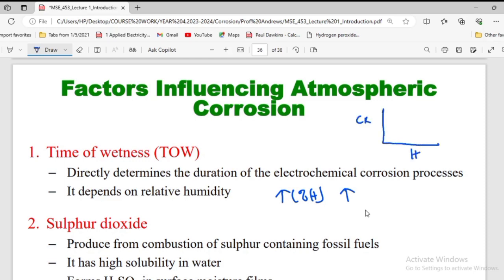So we have the humidity, in percentage, and as the humidity increases, the corrosion rate also increases. But at 70%, pollutants cannot affect the corrosion rate. It will just increase; whether with or without pollutant, the corrosion rate increases with humidity. Now, certain gases also increase the corrosion rate, for example NOx and SOx. When the environment is humid and there are NOx and SOx inside, it tends to increase the corrosion rate. So this is the corrosion rate against humidity.